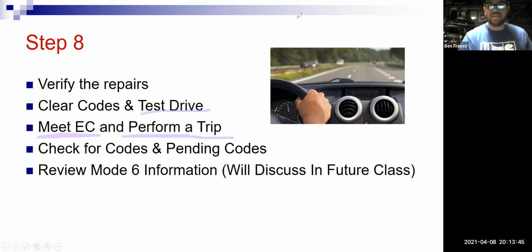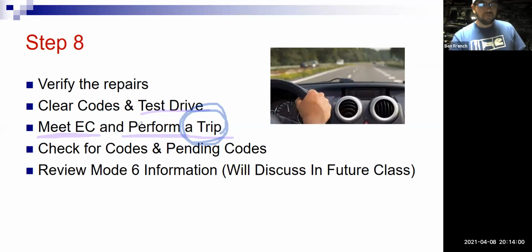Now, if you guys have forgotten what a trip is, in OBD2 terms, a trip is that you've started the car, so it's a key on engine run cycle where you then meet the enable criteria. The computer runs its monitor, it runs its diagnostic test.